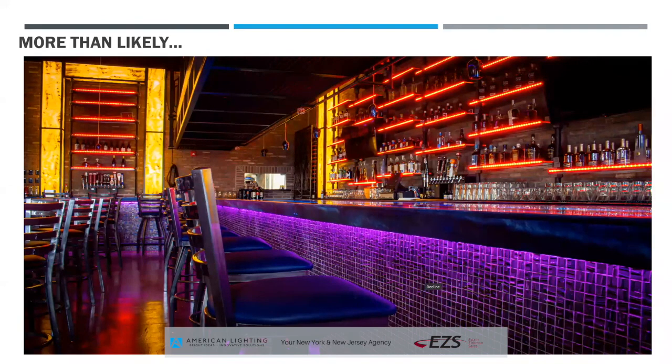Yeah, and that's like all the shelves are the same. So if you wanted each of those shelves to be a different color at the same time, each of those shelves would then be 3 DMX addresses. Right. So if you can see my cursor, all of these shelves, if they're controlled to do the same thing at the same time, and that's RGB tape, all of those shelves are consuming only 3 DMX addresses. However, if each one of those shelves needs to be a different color, then I have 20 shelves times 3 addresses. So now I'm at 60 addresses.